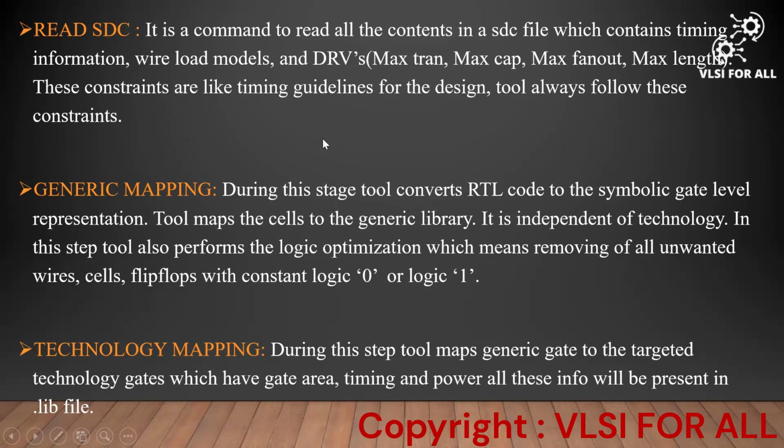In this command, the tool reads the input files which we have given. The constraints, such as max transition, max capacitance, max fanout, and max length, and all the timing-related models like the wire load model, will be present in the SDC file. Those files will be read in this stage, and according to that, the constraints will be applied to the design.